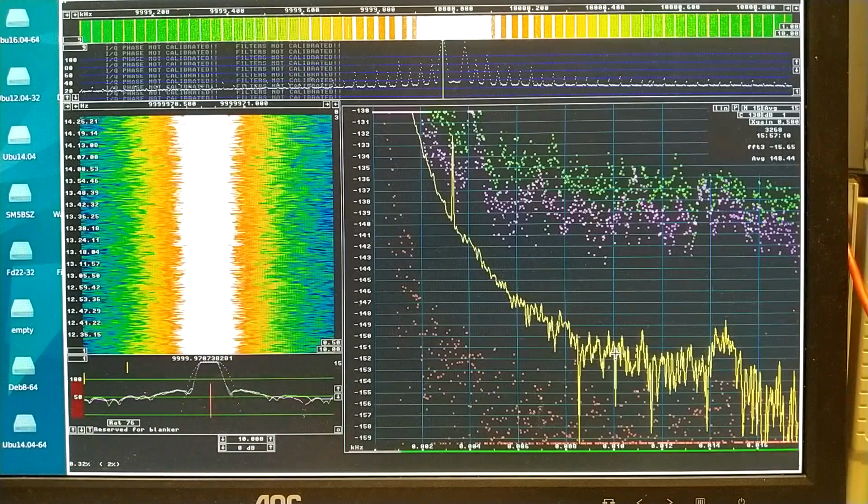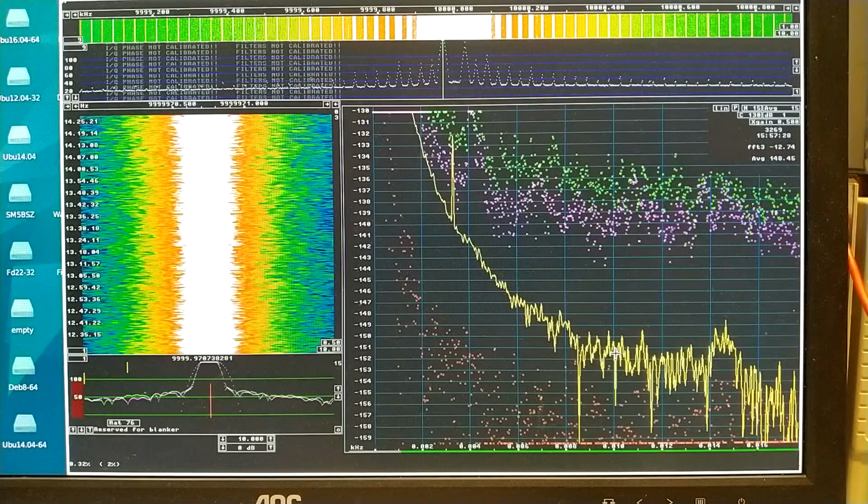And the nominal frequency is 10 megahertz. That is the label I have put on my reference oscillators. So the audio frequency is 10 megahertz minus this, which comes out as 29.262. And if I divide that by 2, I get 14.6.